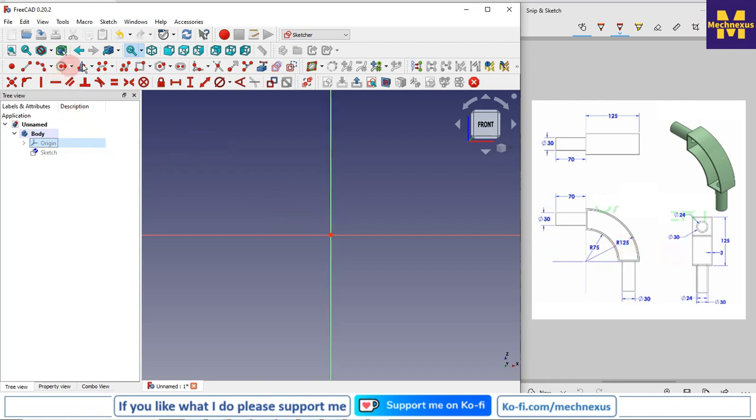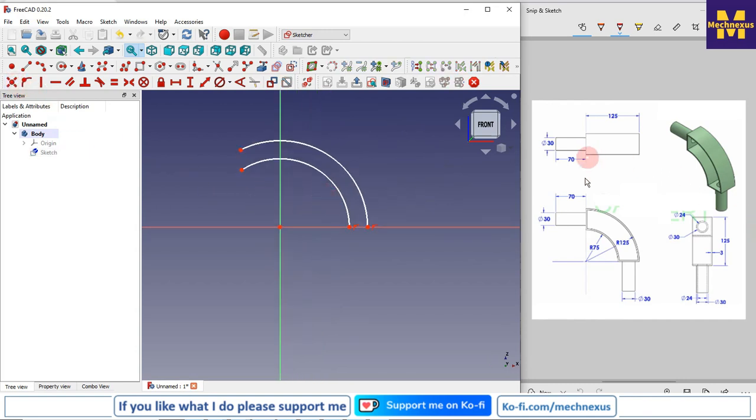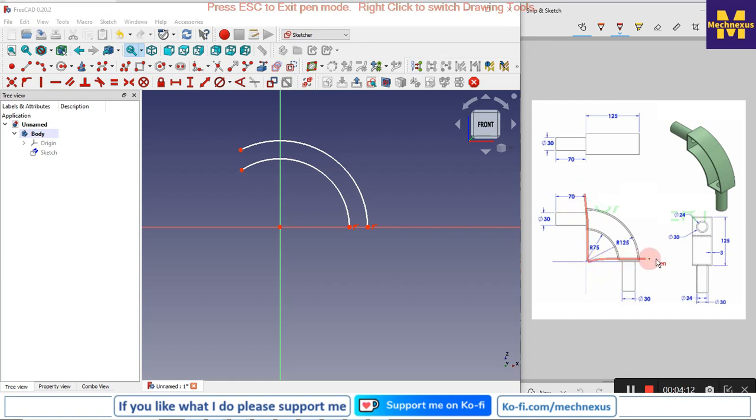So I will simply create a 3-point arc, and I will draw the two approximate arcs, and then I will constrain them with a dimension. These two arcs are concentric, so I will merge them with my origin point. I will say merge, select this and merge it. And now if we see our drawing, it is a quarter of the circle, which means this is totally 90 degrees.